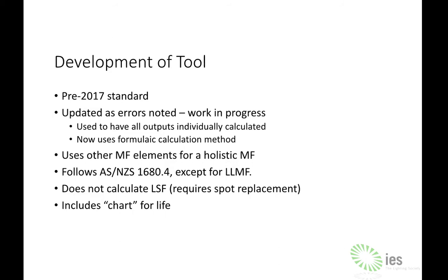But it's ultimately a tool that I originally started doing for traditional sources, and then I said, well, maybe I can apply this to LED sources. I originally calculated LED sources and output a reasonable LLMF at every point in its life, and I spent a lot of time tapping into a calculator. It's good fun. And then I made my own lookup tables, and there were several tables, depending on the data you could stick into it.